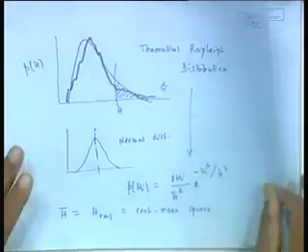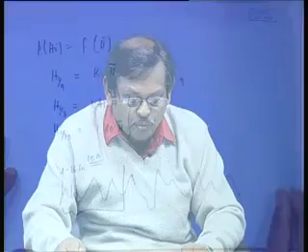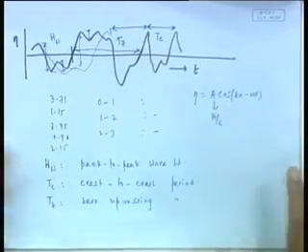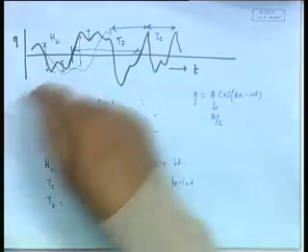Now, having said that, what I now want to tell you. I have collected a long set of raw data, I could statistically analyze it, I find out they follow a Rayleigh distribution theoretically, that means slightly not symmetric. I know what is meant by H 1/3, H 1/10, etc., but does it tell me all? Still, this is only height, as I initially told. Does it really give me the ocean characteristic? The answer is no, because I do not have the time information.